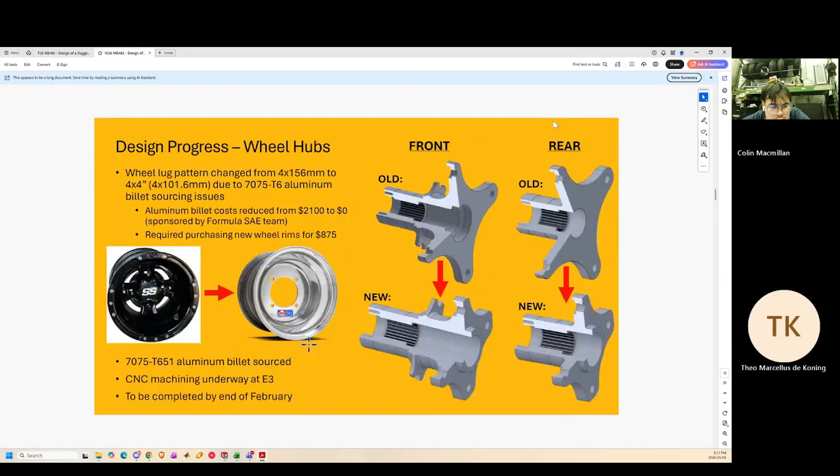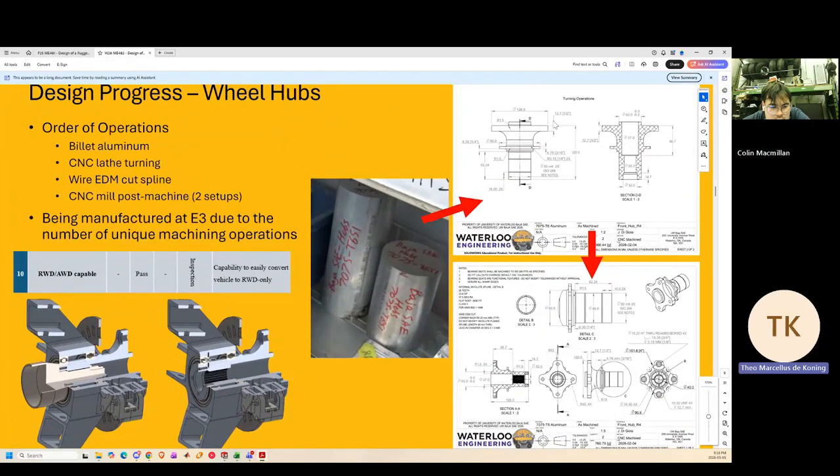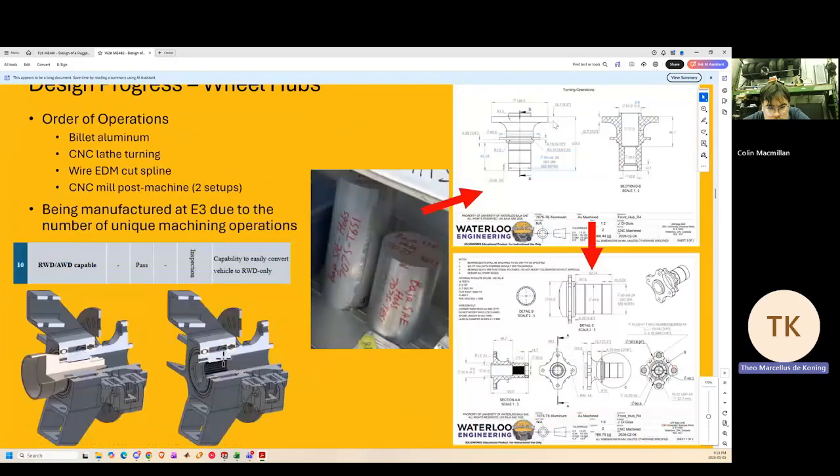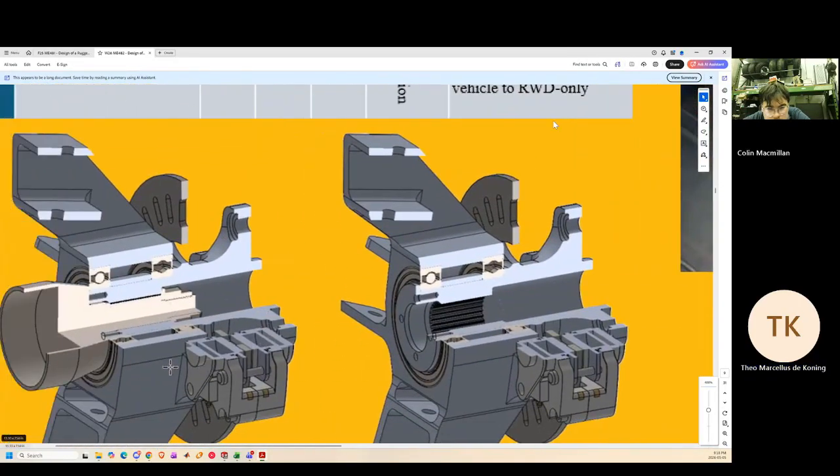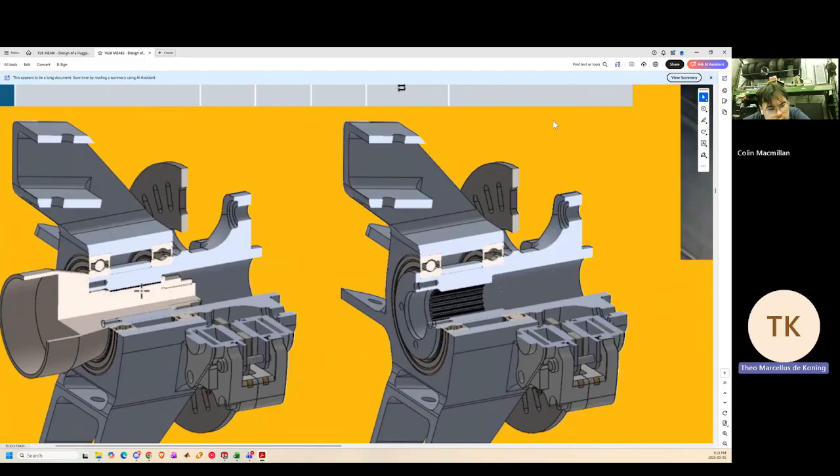Okay. The other nice thing about these new hubs is that in the past, we would rely on the castle nut here to squeeze the whole assembly together to prevent the hub from coming out. But if you see this plate here with 4 holes, this is just a thin sheet metal plate that caps over the hub and pulls against the inner race of the bearing.